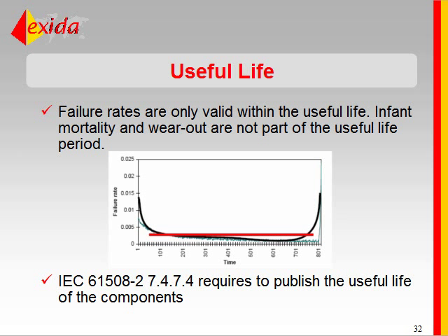Those of you who are experienced electronic designers, there's probably a component that pops into your mind. The notorious electrolytic capacitor. Look it up on the internet. You'll find all kinds of stories about wear-out mechanisms of electrolytic capacitors, and lots of detail about formulas and how to calculate failure rate as a function of useful life. So an FMEDA generates both the constant failure rate during useful life and end-of-life numbers.